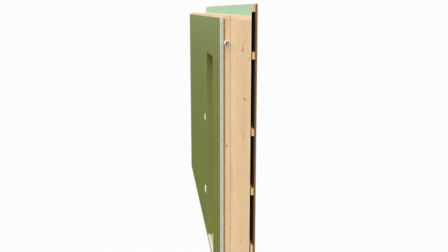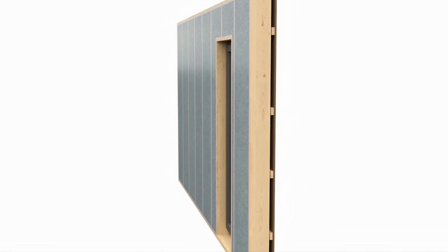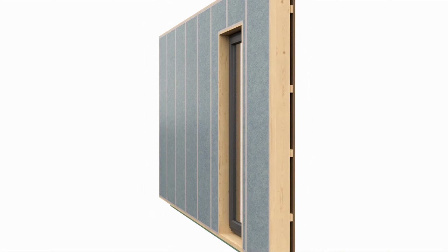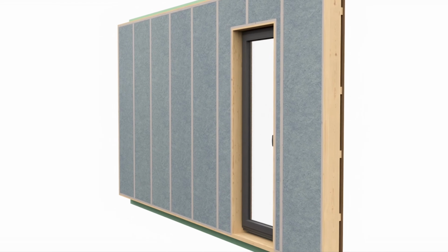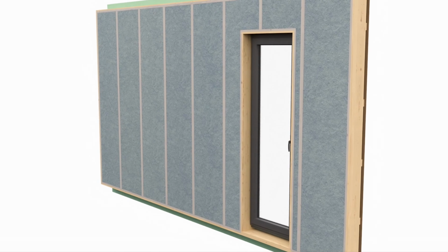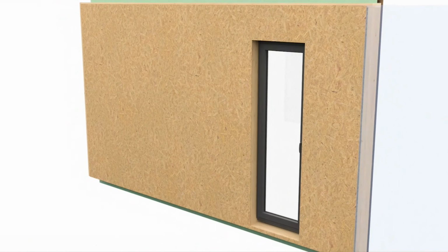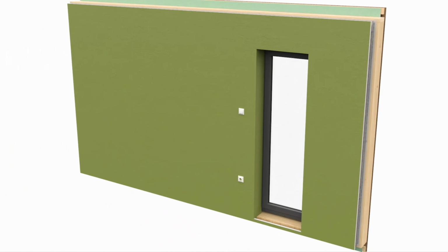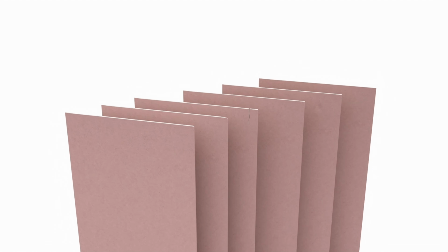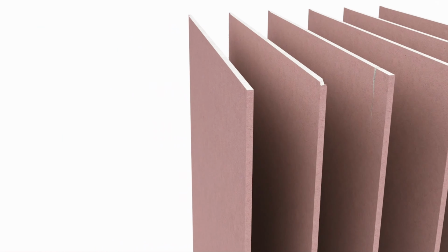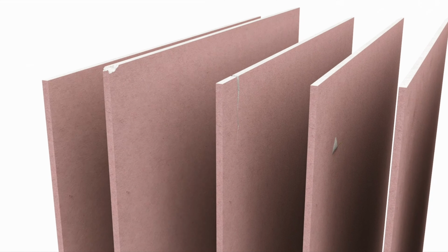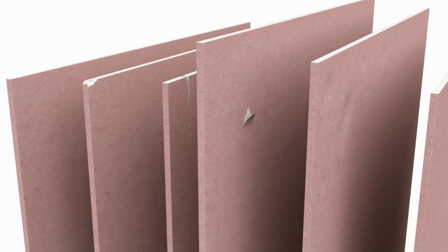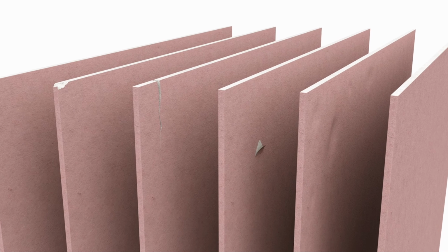If the board coating is installed on an external wall that does not have an internal additional frame, then the vapor barrier film can be installed both directly on the frame or between the two layers of boards. First the lower board layer, then the vapor barrier, and the board layer on the room side of it. Before installing the boards, it must be checked that the boards are intact and free from defects. Defective boards with broken corners, cracks, chips, dents, or other defects should be separated and placed in a designated area.